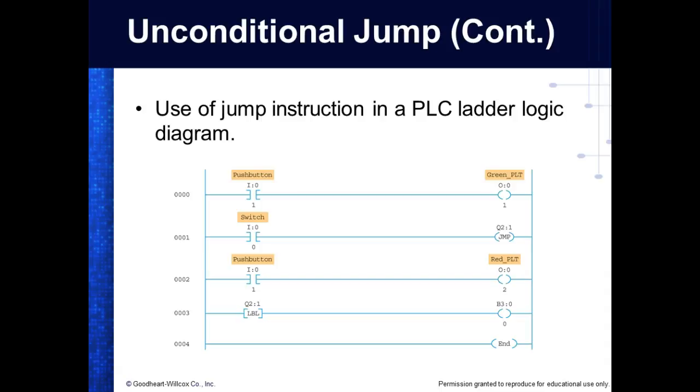So how's this guy right here going to jump? When is it going to jump? It's going to jump when we push the switch. When we have switch one closed, it's going to come here, jump over rung 2, and go to rung 3.